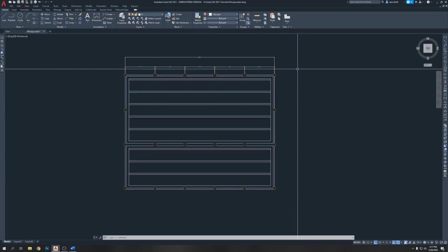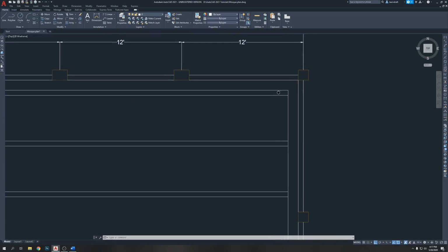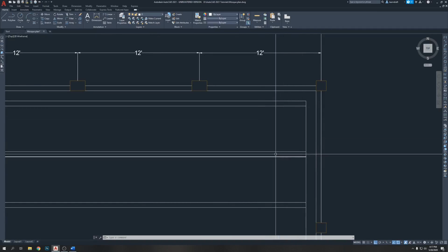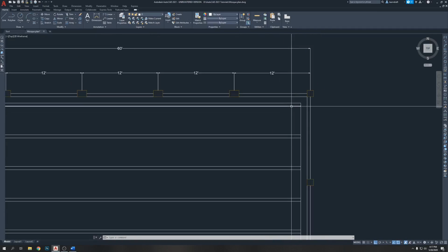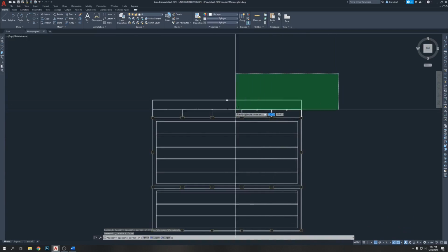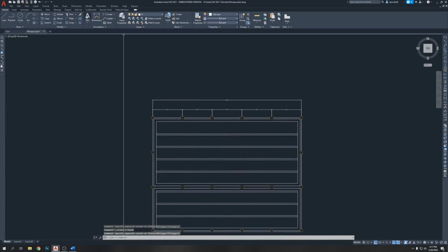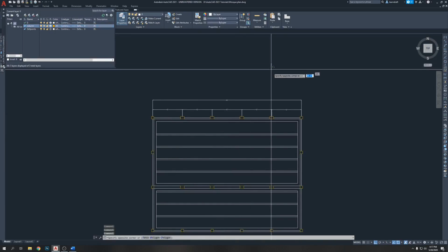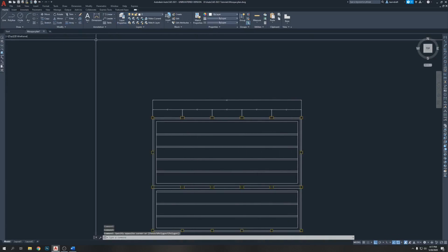Here is one thing, you see, this 6 inches we do not need, because this 6 inches is only for the separation. So what we're gonna do is take out this line, delete, and unlock the column, otherwise it's gonna stay there. Unlock the column, and we saved 6 inches.